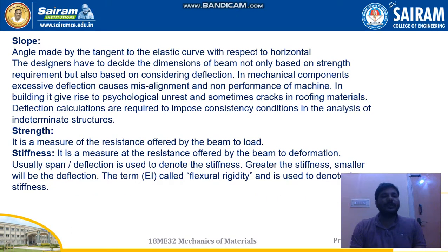Next we are going to find out the slope. This is very important. The slope will vary from one point to another, that is from one point of load to another. For example, for a point load the shear force will be constant and the bending moment will be linear. Similarly, for a UDL, the shear force is linear and the bending moment forms a parabolic curve.